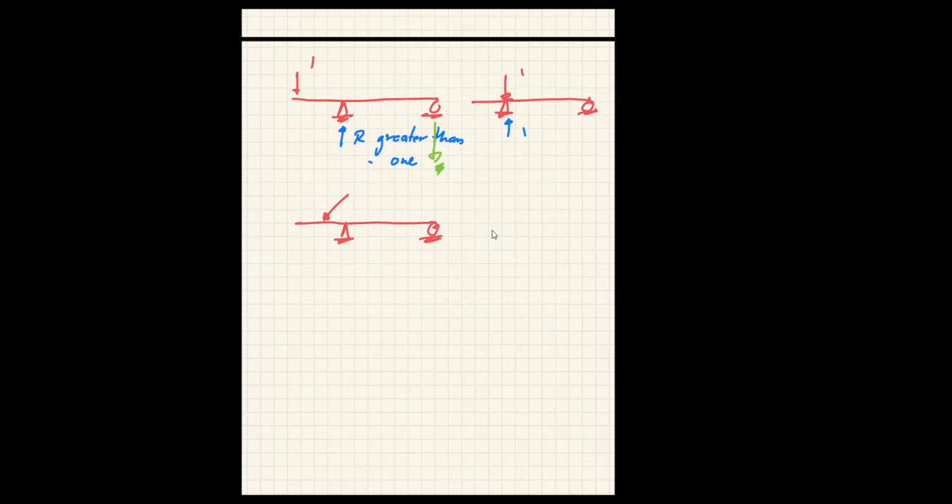Okay. So what would happen? I would place sort of a roller here, so that this shear will go free to go up and down, down and up like that. Okay. So now we have two pieces of the free body diagram.